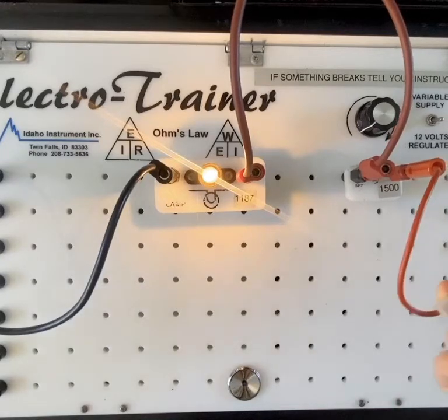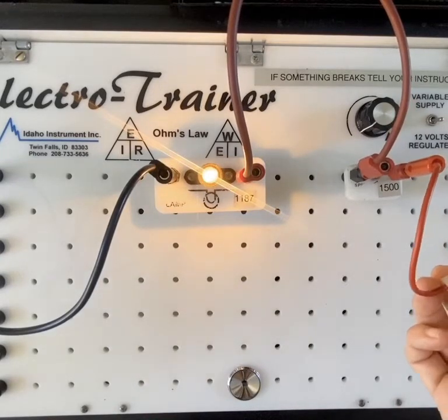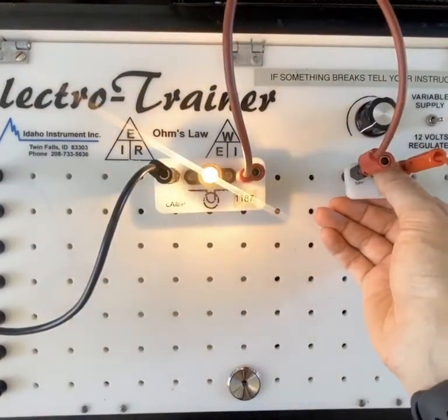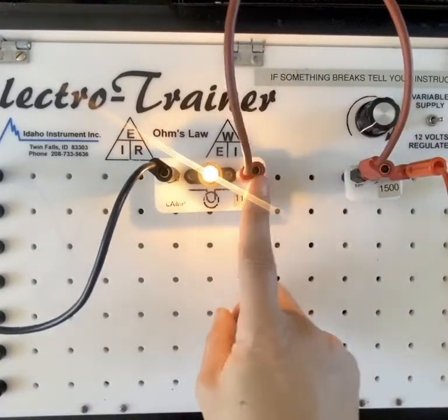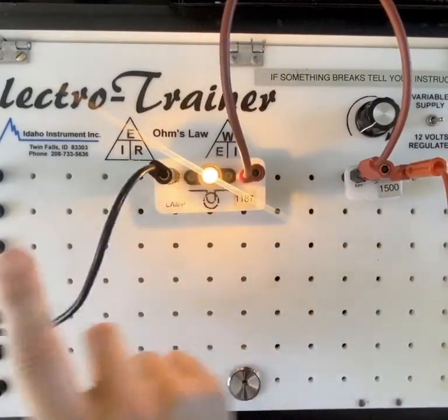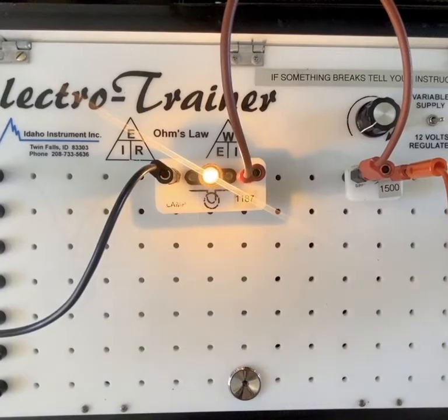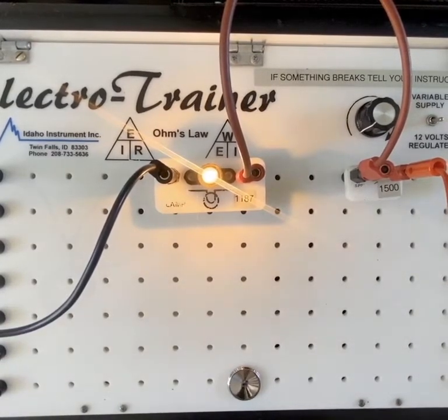Now, just to do a quick review as we're looking at our components, we've got our fuse, we have our toggle switch for our circuit control device, and we've got our power path going into our load, then going to our ground path. Now, let's take a look at what happens. We know what happens math-wise when we add another bulb in series. We know that we're adding more resistance to the circuit, which is going to drop our amperage, and we know that voltage is going to have to split up, but what does that really look like?